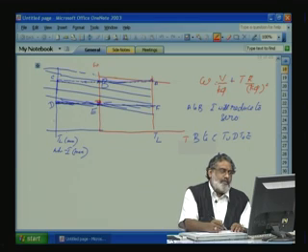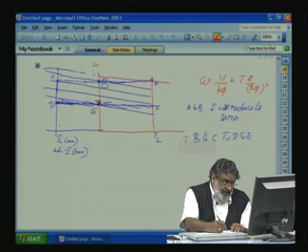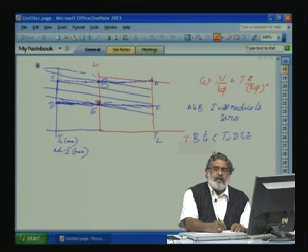This TL maximum, this point, has to be limited by your controller. That means through the applied voltage you have to control, so that always maximum negative torque is applied to the motor, or maximum current is taken from the machine such that the machine will decelerate.